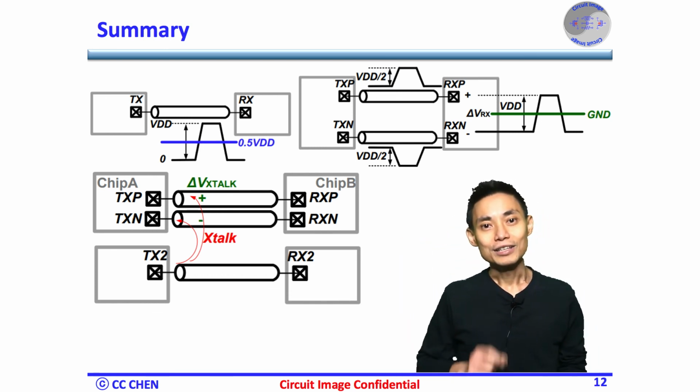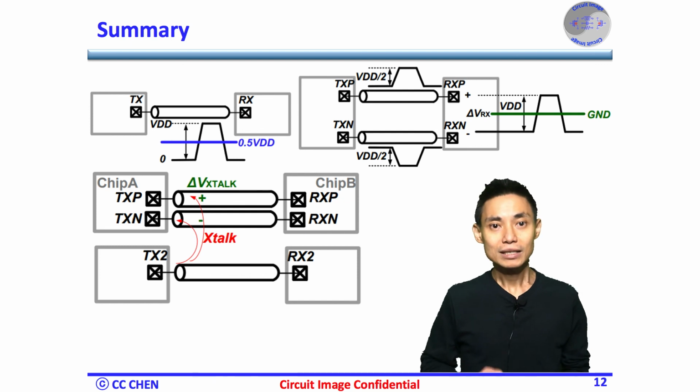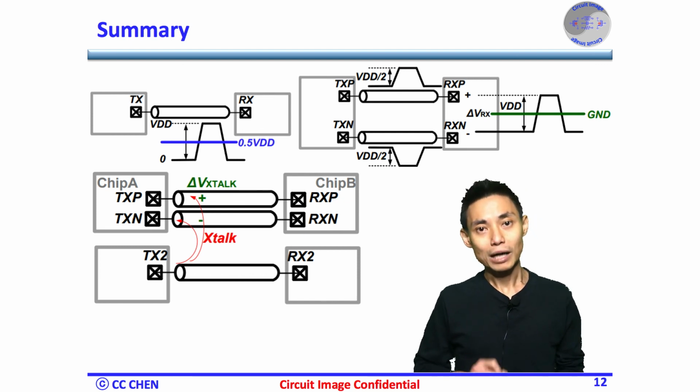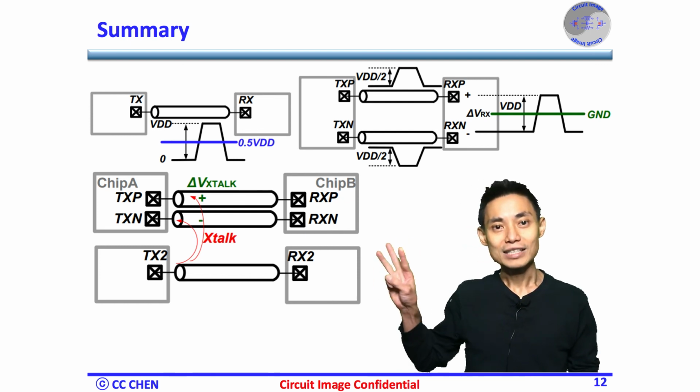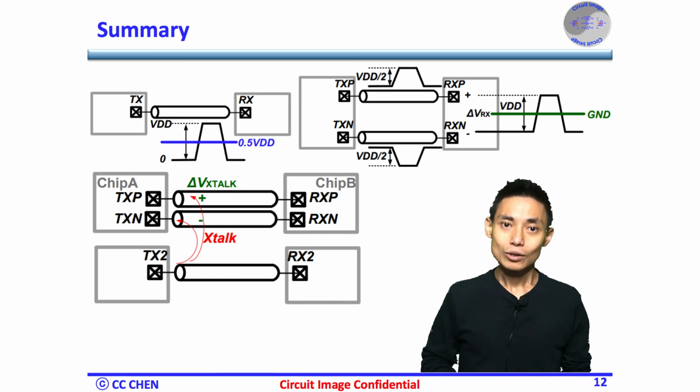Second, the differential signaling's self-introduced power supply ripple can be reduced by reducing its switching current while maintaining the equivalent swing for noise margin. Lastly, the 0 or the self-reference level of the differential signaling will mitigate the reference distribution issue, and there is no challenge of generating any required voltage level.